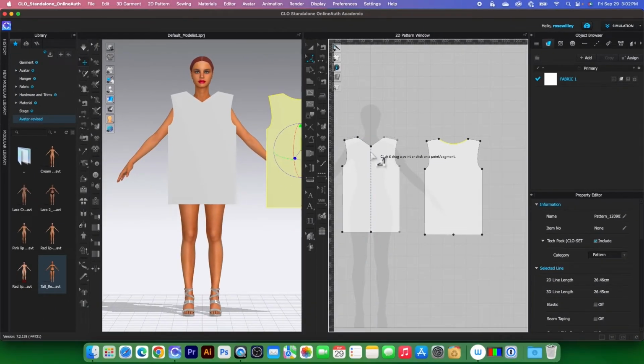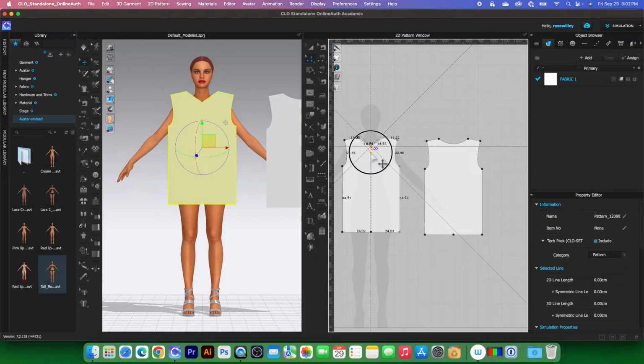And then the front, we want to drop the front neck a little bit here. Simply switch the tool back to the edit pattern tool, click once and then press shift and then drag it down, okay? How about like that? After that, we want to curve this neck a little bit. Use this edit curvature tool, okay? Click on it and then drag it in, just like that.